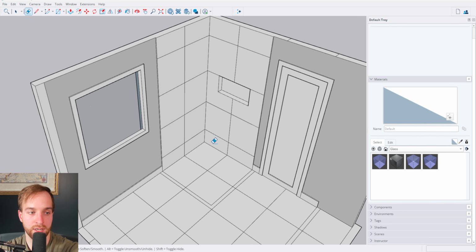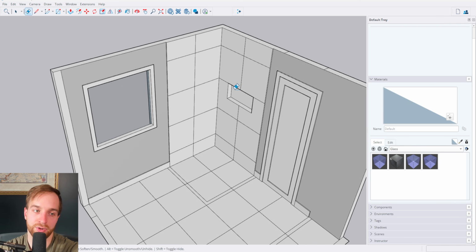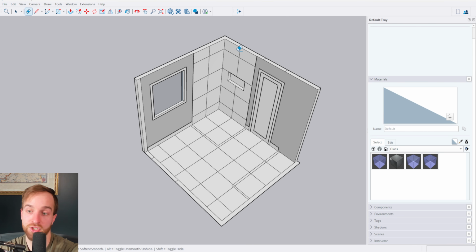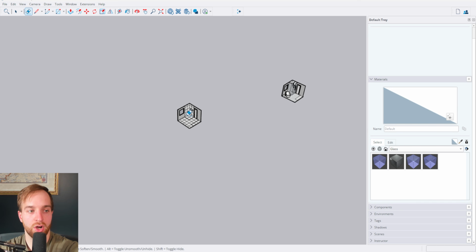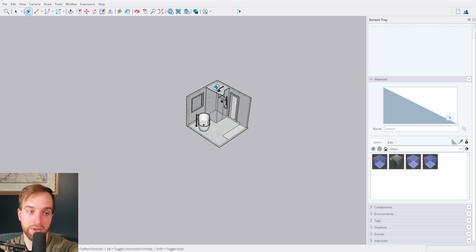We could say 1 tile, 2 tile, 3, 4, 5, 6, 16, 17, 18 tiles. Maybe we add another couple for the niche, 20 tiles, and then another couple extra, say 22 tiles for the shower, if we wanted to be efficient with it, right? And have some extra for oopsies or manufacturing, transportation, all sorts of different mistakes that could occur. All right, so there's the showcase for something like a tile layout and why that might be useful.